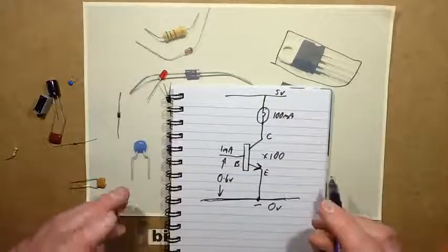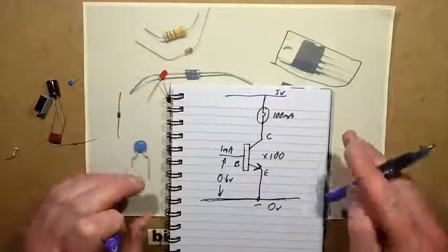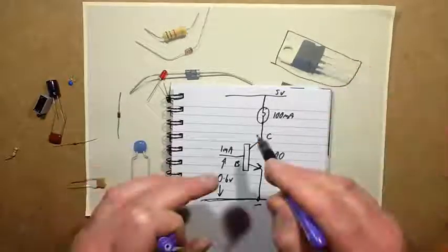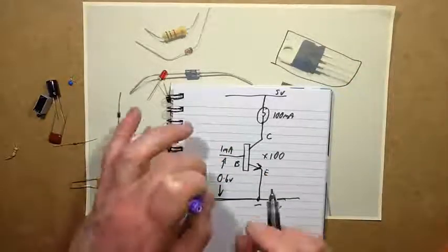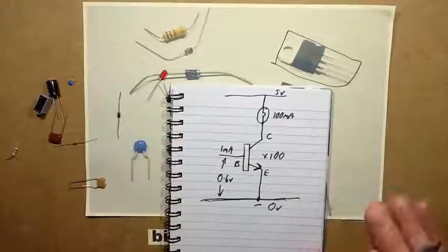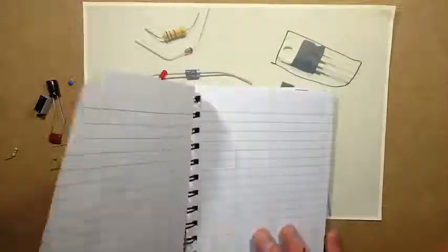So you get a hybrid called an IGBT, an insulated gate bipolar transistor, which is almost like a traditional transistor with sort of low gain, but with one of these transistors on the front of it, so it's very easy to turn on. It can switch massive currents, and it's really a robust transistor. But you can find all that online if you actually look for it. This is just a basic guide.